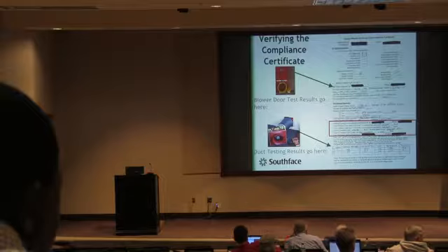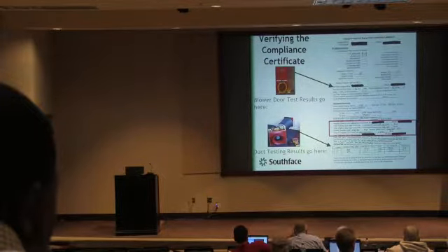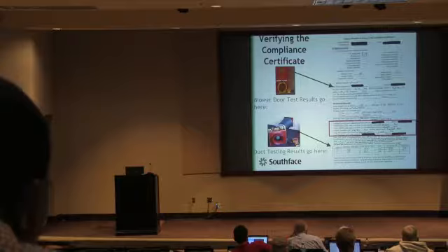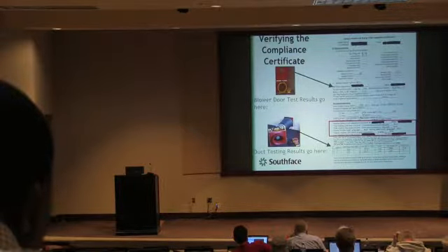Exactly right. And it is probably one of the least enforced and most important requirements of our energy code, and it's what you just described. Even folks in the heating and air industry are like, I come out, I look at the square footage, so many square feet per ton, one ton for every 400 or 500 square feet, basically. I know the square footage, I know the size system that I need, that's what I put in the house.